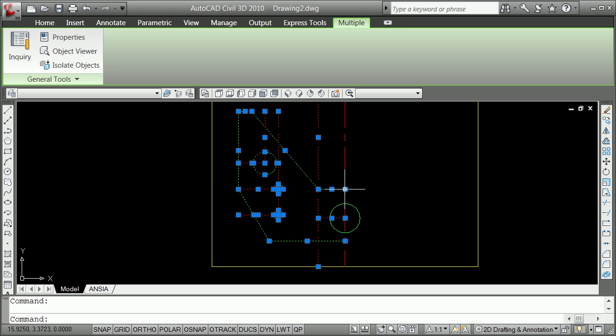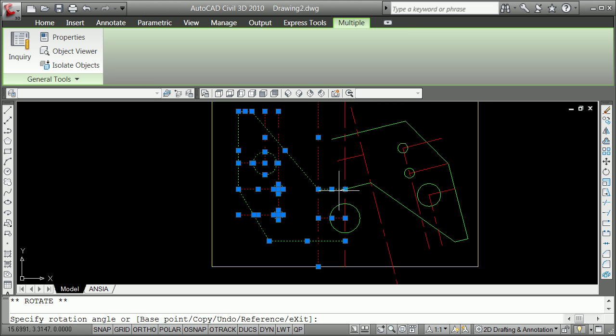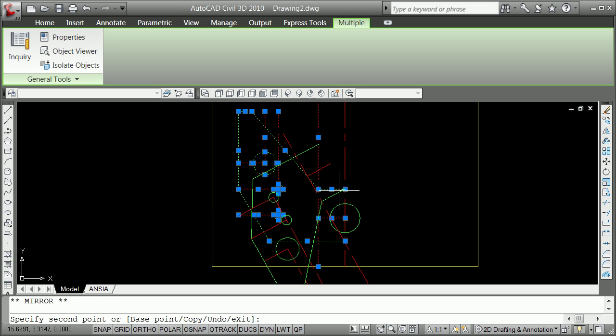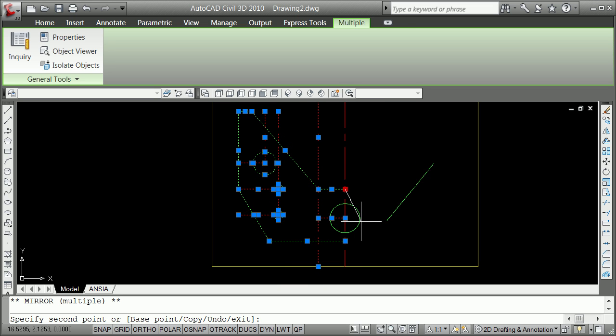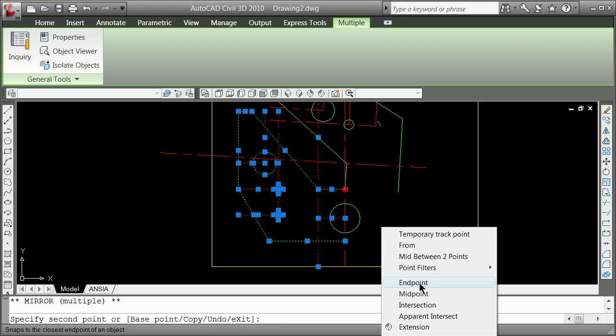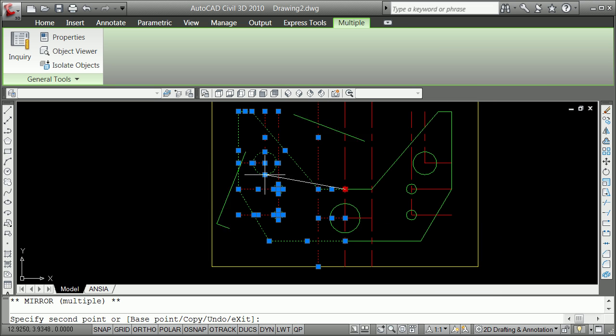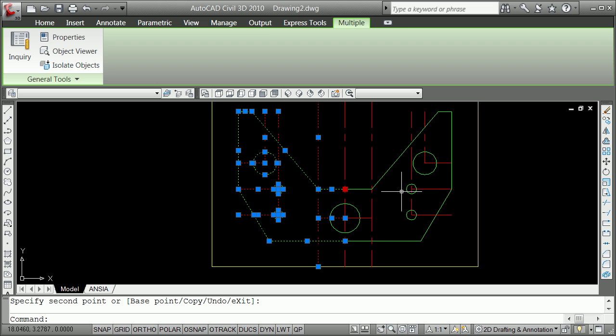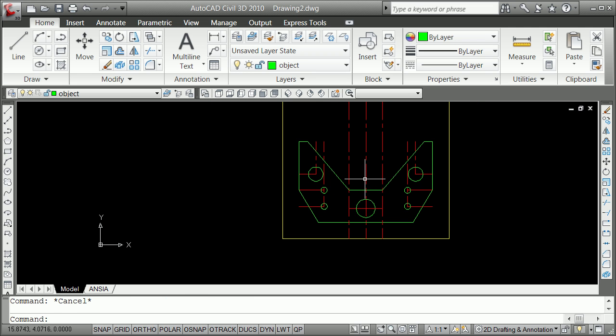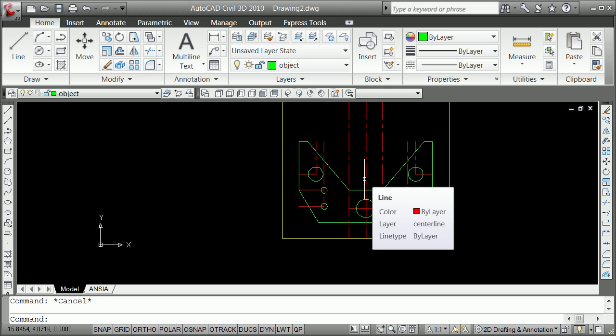Now I'm going to left click over some point. It doesn't necessarily have to be the point that's going to be our final spinny point or rotation point, but it helps. Left click, and then I start spacebarring through. Spacebar, spacebar, spacebar, spacebar. You have to remember C for copy, and then give it the second point, shift right click, maybe the end point there, and you have this part completely done. And you'll see later, when you get into modeling, why it's a better way to do it than to draft both sides of that.